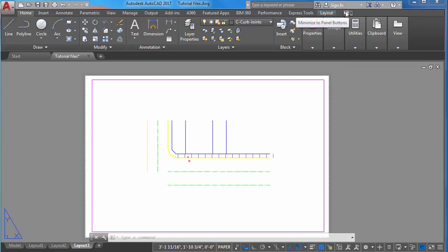The file we just loaded will tell AutoCAD to associate certain colors with certain line weights. So certain layers will have a color and they'll be thicker or thinner lines. We've given you several ranges of line weights. If you'd like to add additional line weights, please talk to your instructor about modifying the file for more line weights.